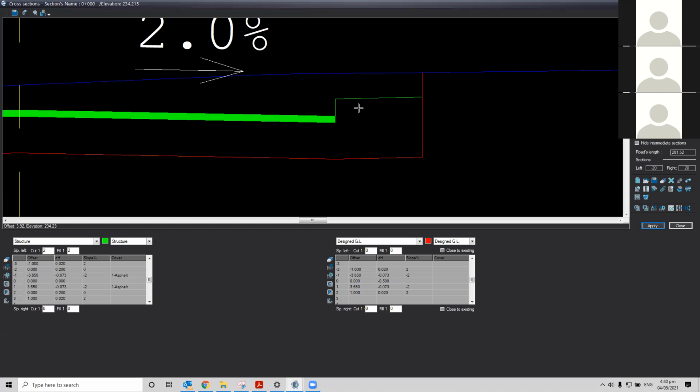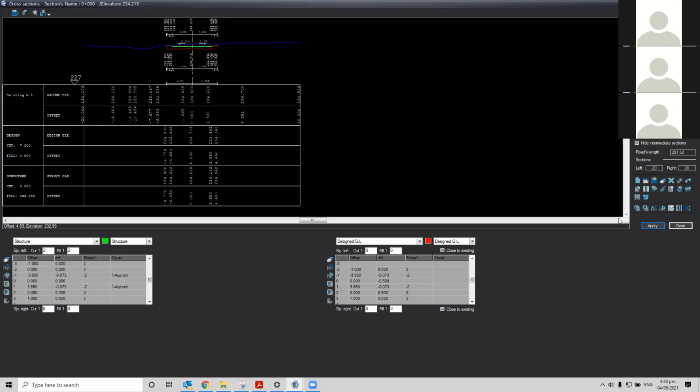So what you have to do, go to the design, stand on segment number 2 and press enter on the keyboard. Here you have to enter also a step, so make it 0. And on the DH, you are moving from -5, and you have 70 now and you want to remain at 20 cm, so you have to put 0.5 here. Yes, apply, and zoom in.